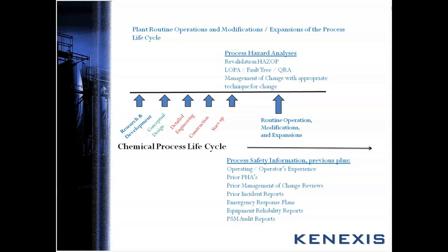You also have, unfortunately, actual incidents that have revealed scenarios that weren't previously identified in the previous PHA. You also have safeguards that you didn't know you had that maybe weren't credited when the first PHA was done. You also have changes in your safety instrumented system. It's also possible positive changes might have happened where you could maybe find some additional safeguards you didn't identify.